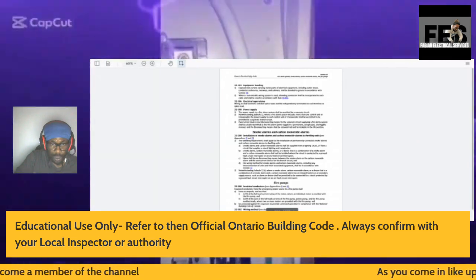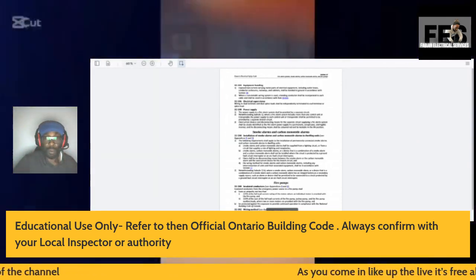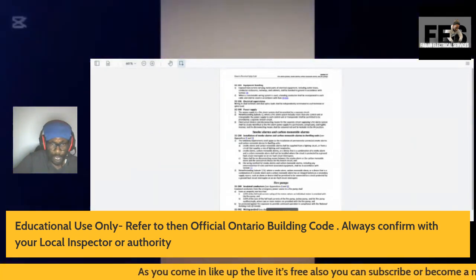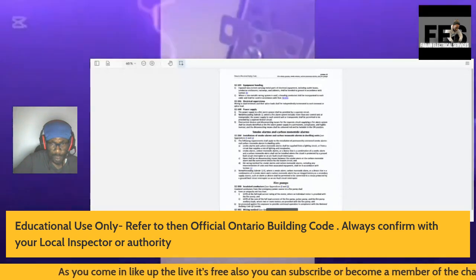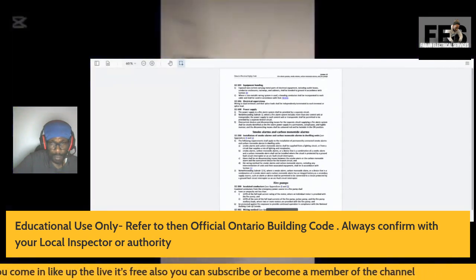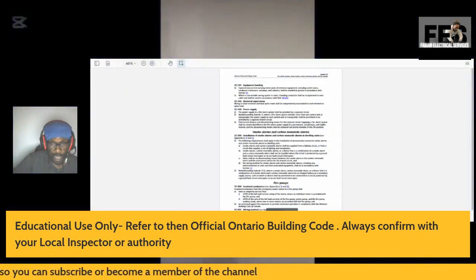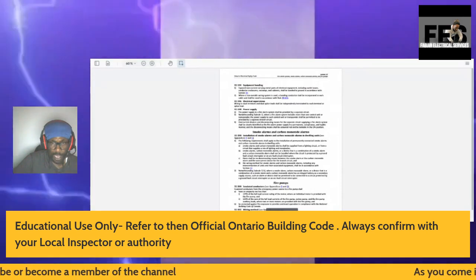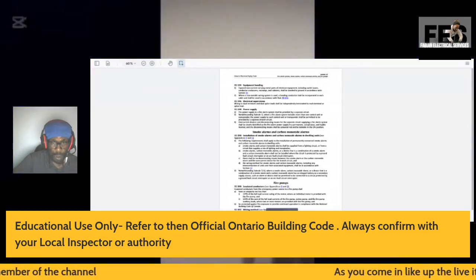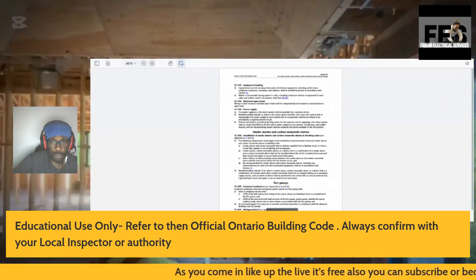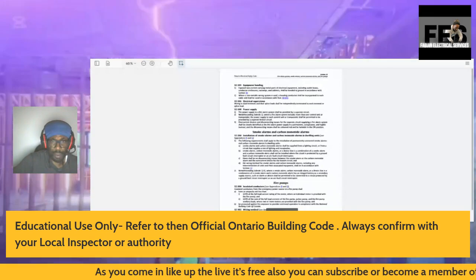You're going to see that I do supply the smoke alarms with a lighting circuit. That's how we do it in Canada. We provide the power through the lighting circuit, and it has to be straight power, no switch to turn off the smoke alarm. You cannot have a disconnect in between.